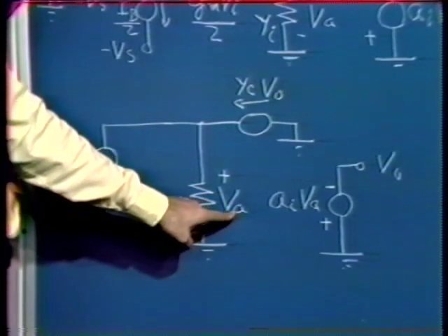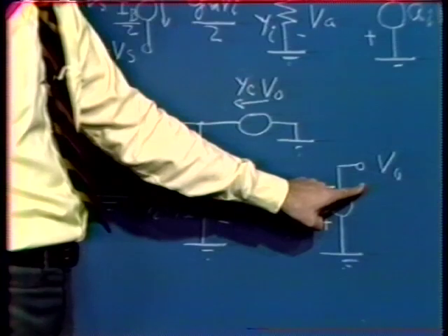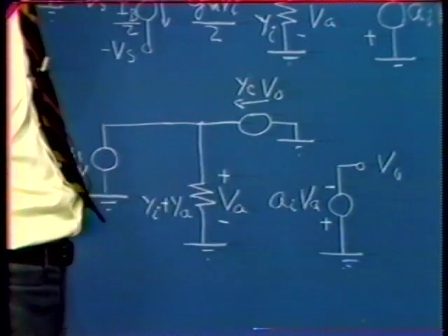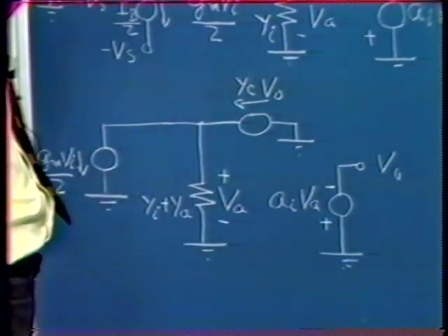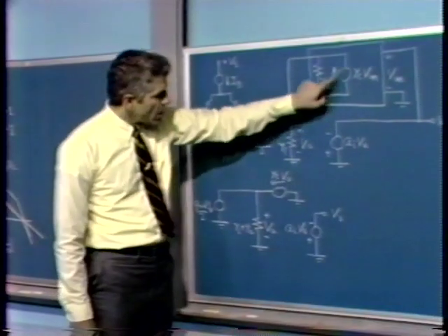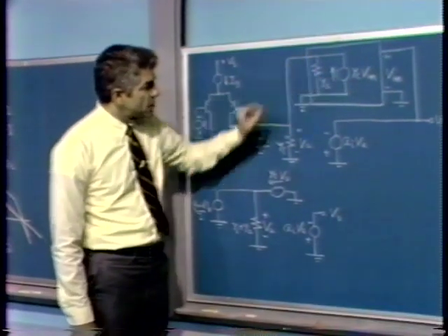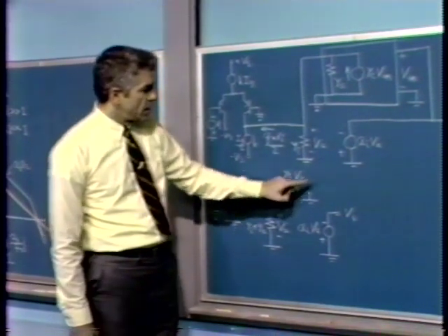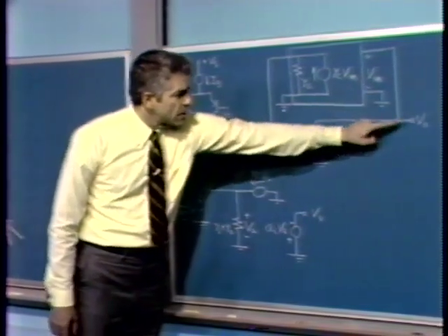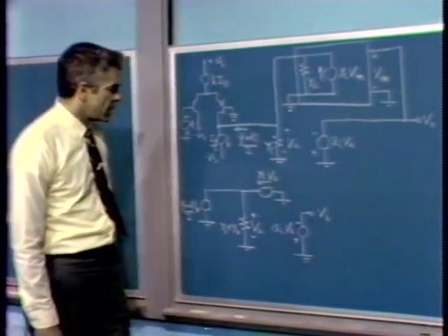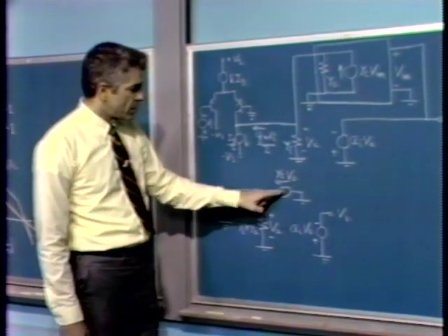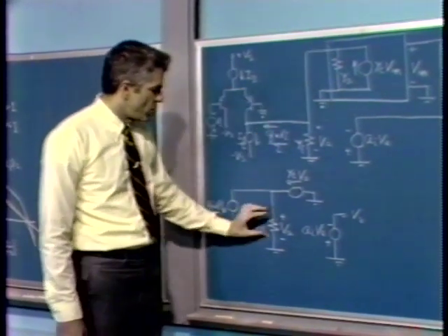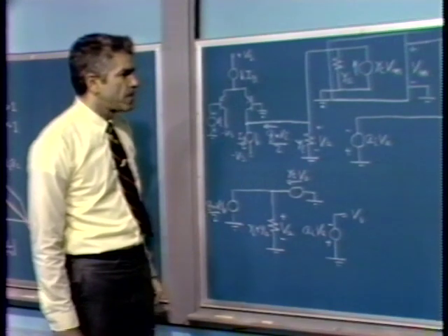The voltage across that admittance is Va, and the output voltage, as it was above, is simply Ai times that voltage V sub A. We complete the minor loop, or model the effect of the two-port network as far as its feedback effect, simply as a dependent generator whose magnitude is Y sub C times now VO, recognizing that VO and VM are identical. And so we represent the dependent generator associated with the two-port in this way. We've already taken care of the output admittance of the two-port since we've lumped it into this admittance.